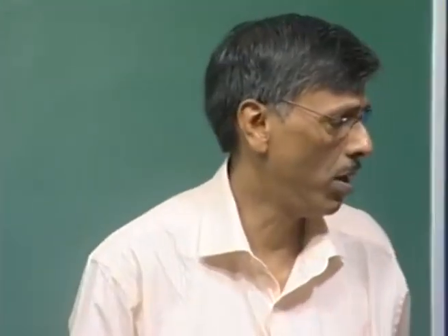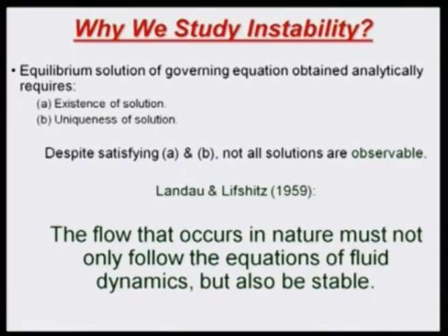Okay, in yesterday's class we started discussing instability and receptivities, and what we did was we focused our attention on Reynolds pipe flow experiments, where he pointed out that the critical Reynolds number could be raised as high as that by controlling the disturbances, and that made him observe also that this kind of growth of disturbance could be related to nonlinear instability, because you need a certain magnitude of the disturbance to trigger such instabilities, right.